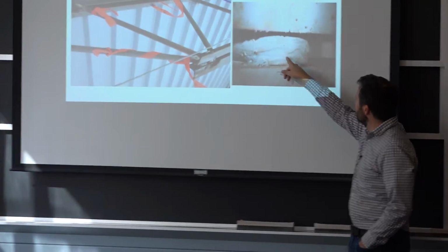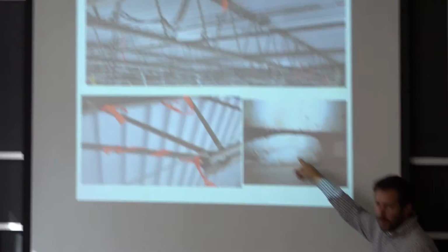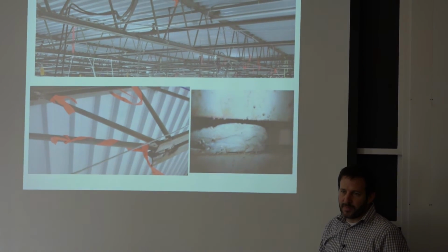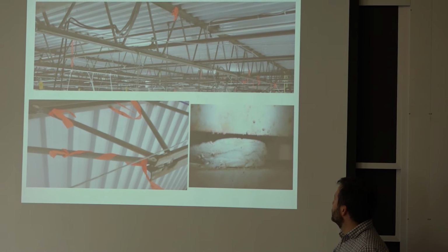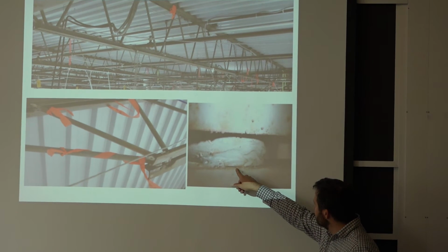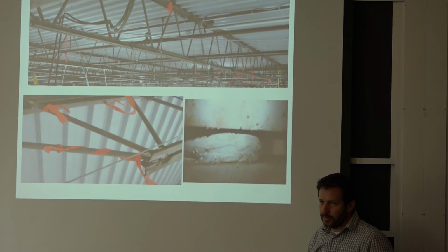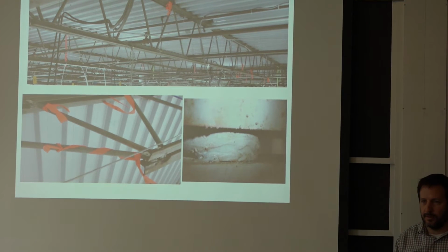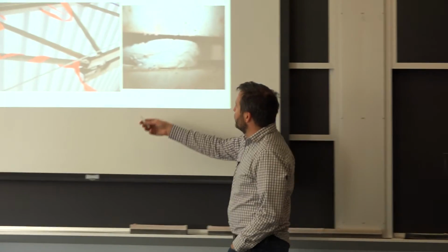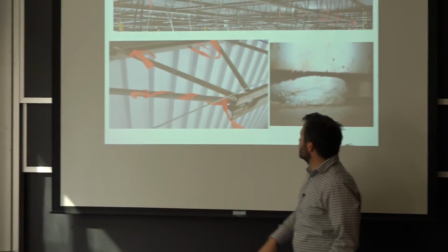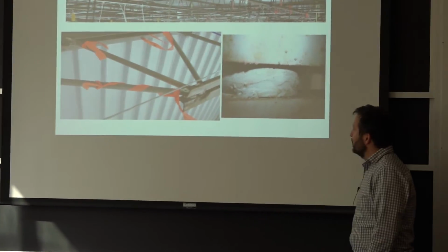So the same situation, where they welded a lot on the bar and didn't weld against the angle. So it broke. You can see the spacing, and then there's a repair weld because somebody got scared. And that was the first diagonal, this one here on the joist, that was bigger and supposed to be stronger.